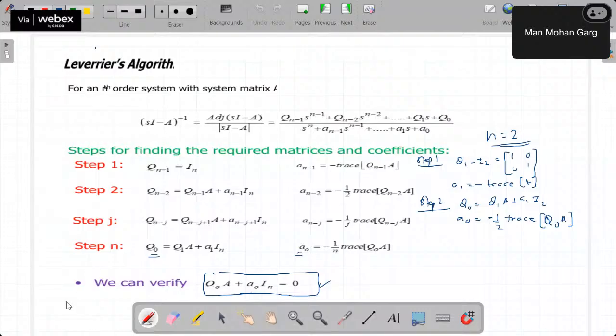Can we neglect the modes with small time to reduce complexity? Does it make any effect? Yes, it may make an effect. You can neglect only if whatever action is taking place affects the operating point very slightly. But if it has a long or large impact on the DC operating point, then we cannot.